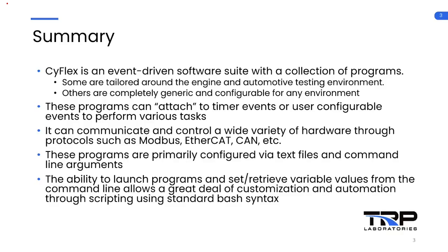So if you have a laminar flow element in your testing facility and you need to read those values, you're going to make the decision to launch our LFE program so that you can take those raw values and then convert them to mass airflow. Some of these programs are tailored around the engine and automotive testing environment. Things like our engine control task, it's very engine testing specific. And then others are completely generic and configurable for any environment.